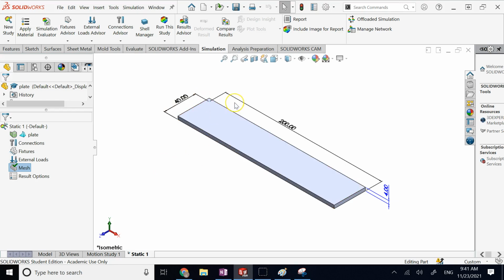Now, for a simple problem like this, it's no big deal whether you use 2D or 3D. But when the problem gets more complicated, it does matter whether you consider the problem to be 3D, which is using solid tetrahedron elements, or you just consider it 2D. Because let's say here, if you move along the y-axis, nothing would change. Let's say here I put a fixed support on the back plate and I put some load on the front plate, right, and make it a cantilever beam. So really going up and down, moving in the height direction is not going to add much to the analysis.